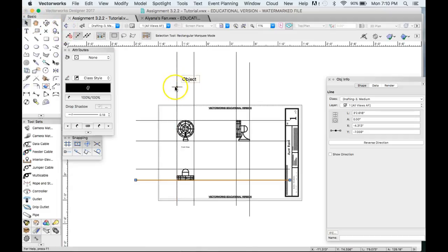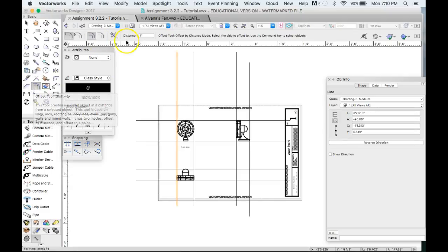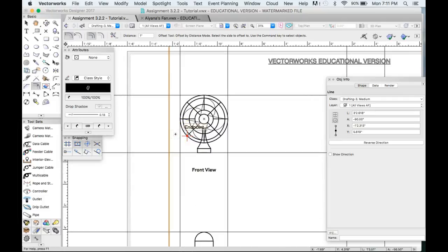So first, what we're going to do is just offset these. We're just going to go to the offset button, and right now it's at 1 inch. Now I'm not inside of a viewport annotation right now, so all inches are real inches in real time on this piece of paper. So let's see what this looks like. I'm going to go ahead and go this direction. Alright, does that feel like it would be too close for the first dimension? No, it doesn't really.